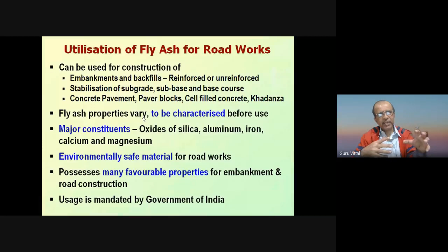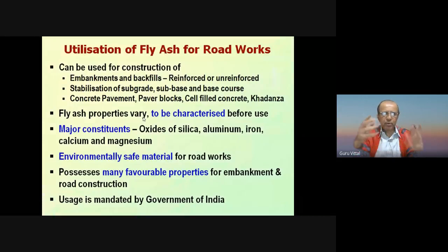Whatever fly ash you get in Kota will be entirely different from whatever fly ash you get in Suratgarh, because in Suratgarh it is lignitic fly ash. Whereas in Kota, as I understand, they don't use lignitic fly ash, so the properties will be entirely different. So we have to test the material, and accordingly it has to be used.